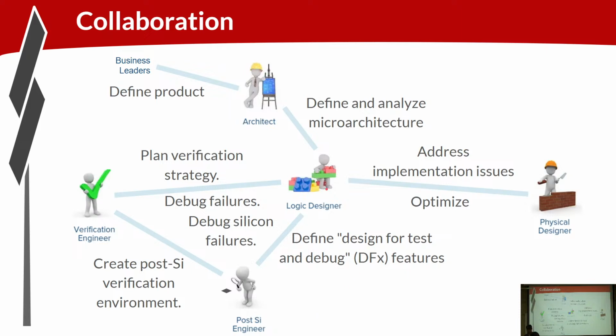And as I said, the post-silicon engineer is doing a lot of preparation, working with the logic designers to feed in these features, which would be referred to as design for debug and test, especially to make sure those features are in the RTL model. Verification engineers and post-silicon engineers are also working together closely on the environments to make sure they have a post-silicon environment in place for verifying the physical silicon and leveraging as much as possible from the pre-silicon work.